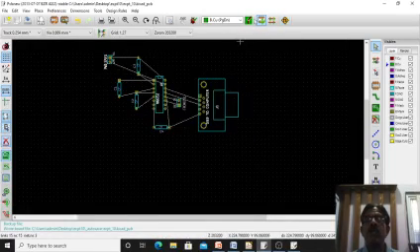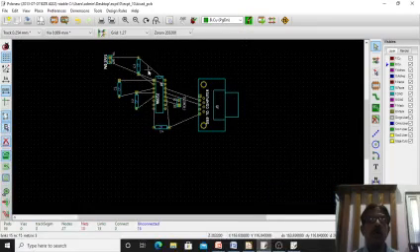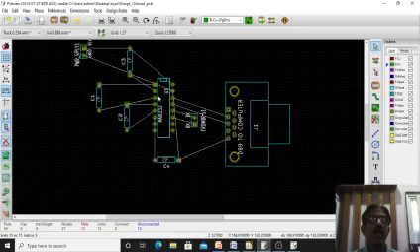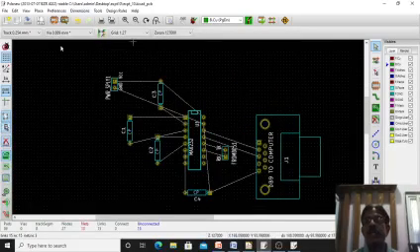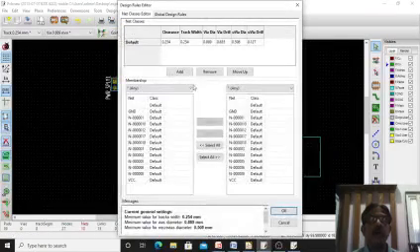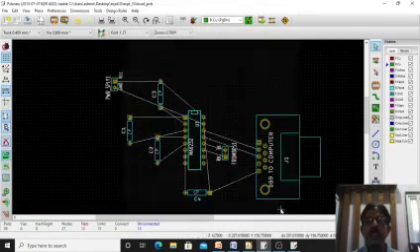Then what you have to do is, next click on this, then right click here, global, move and place, move all the components. If you do this step, all the components will come here. Okay, then arrange them correctly. I have arranged all the components correctly. So then last step is, I have increased the width of this a little bit more. Okay, I have taken it as, for example, 0.4, so that tracks will look better.